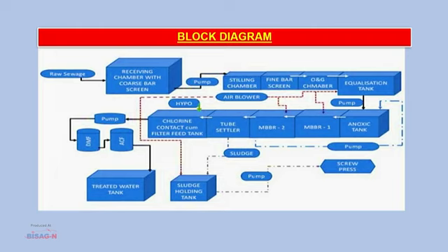Then comes stage 12. To recirculate residual biomass with sewage into the anoxic tank, pumps are provided which take sewage from the bottom of MBBR 2, where an outlet riser screen is placed.